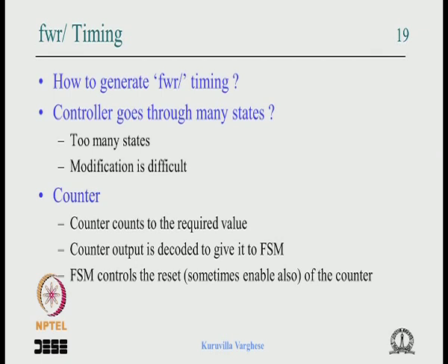If at the beginning, depending on the range of the access time of the FIFO, you choose a counter width to accommodate all possible ranges in future, then only the decoder needs to change. It is very simple, as a decoder is many times an AND gate with inverters. So it's very simple to redesign. So that is what we are going to do.